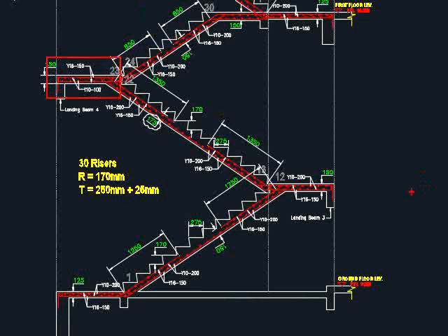That means these two landing slabs are going to be at the intermediate height of the building, where there will be landing beams. This landing beam is not seen in your structural key plan because the key plans are meant for the ground floor and the first floor. Therefore, you will need to clearly indicate where the locations of the landing beams are.